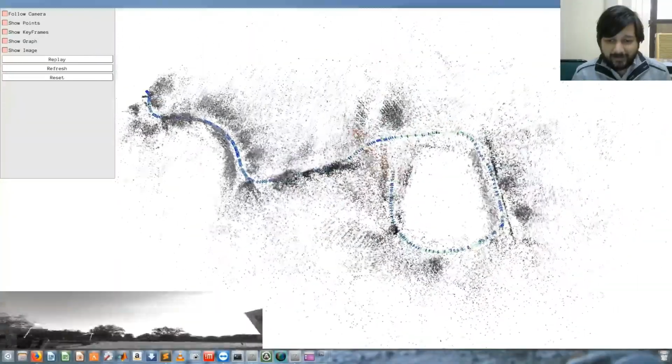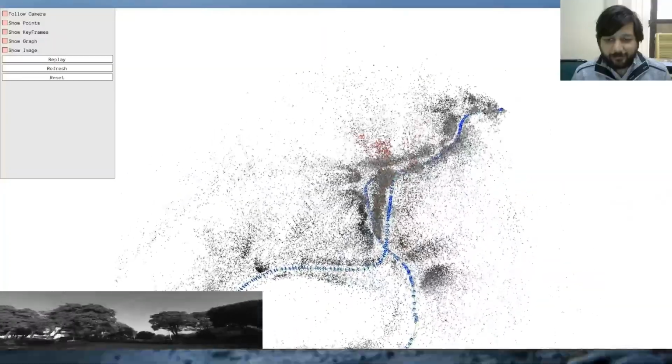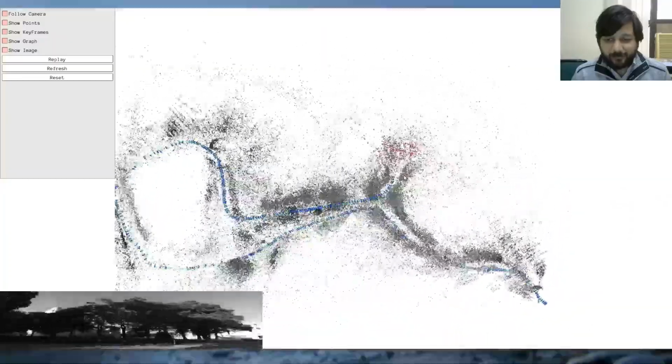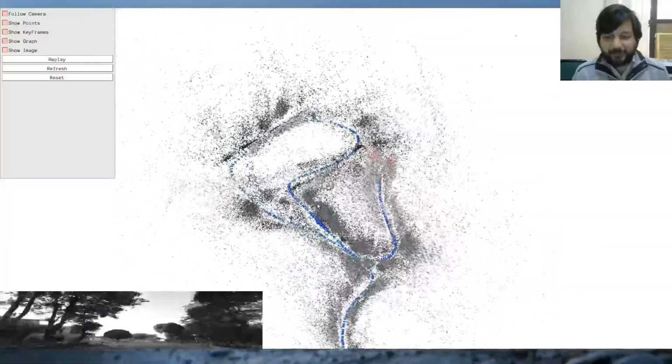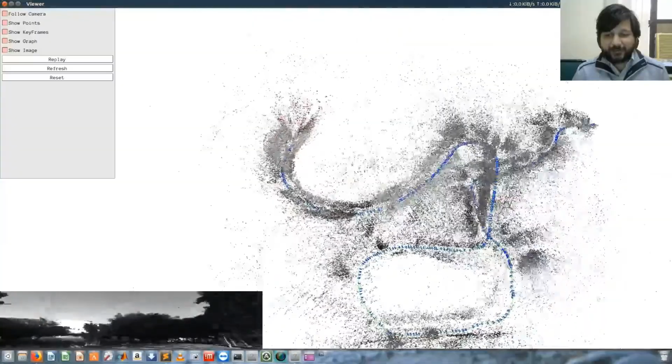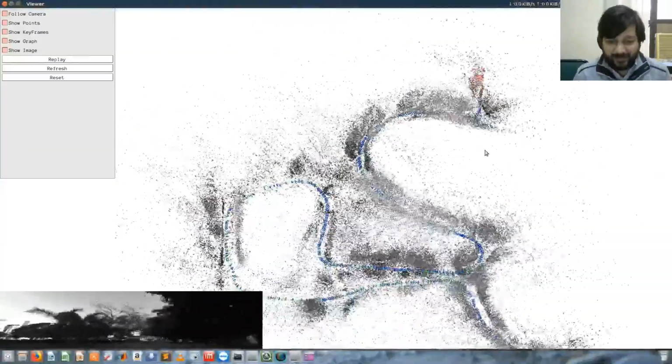And the green one is the computed part, and the blue is the position of the robot at every point of time. That's what we calculated as Q0, Q1, Q2. So it's doing SLAM, it's calculating its own position based on the black dots or the landmarks. Now you also know practically how many landmarks are possible, and using that, it is correcting the black dots' positions or adding new black dots.